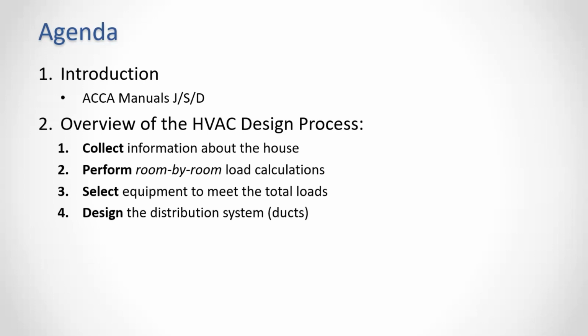It's very important that you know what the house needs. That's what the load calculations tell you, what the house needs. You cannot properly size equipment for a house unless you know what the house needs. It's not a tiny band, but there's a narrow band above and below the load calculations that if you're outside that band, you're too big. And if you're outside the band on the other side, you're too small. And both of those can cause issues.